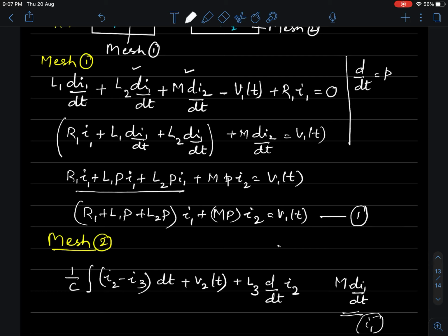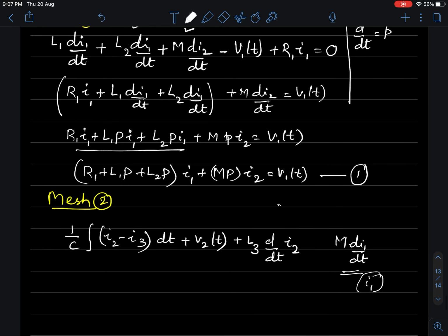That means in L3, the dotted end is at the bottom, and the EMF is going to be positive here. If this is L3, the EMF induced will be of this nature: positive, negative. Okay, so the downward is positive. So when we go in the clockwise direction, we hit positive first, then negative. Positive to negative is a drop in potential. So drop is taken to be positive, and this is now positive.